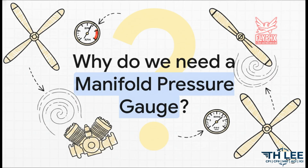Now, you might be wondering, why do we even need a manifold pressure gauge in something like this aircraft? In a fixed-pitch Cessna, your RPM gauge tells you exactly how much power the engine is making. But remember, the governor maintains a constant RPM no matter what you do with the airspeed or throttle. Because the actual RPM is masked by the governor, we absolutely must monitor the fuel and air pressure being shoved into the engine's intake manifold. That manifold pressure gauge is telling us exactly how much power our throttle is commanding, completely independent of how fast the blades are spinning.